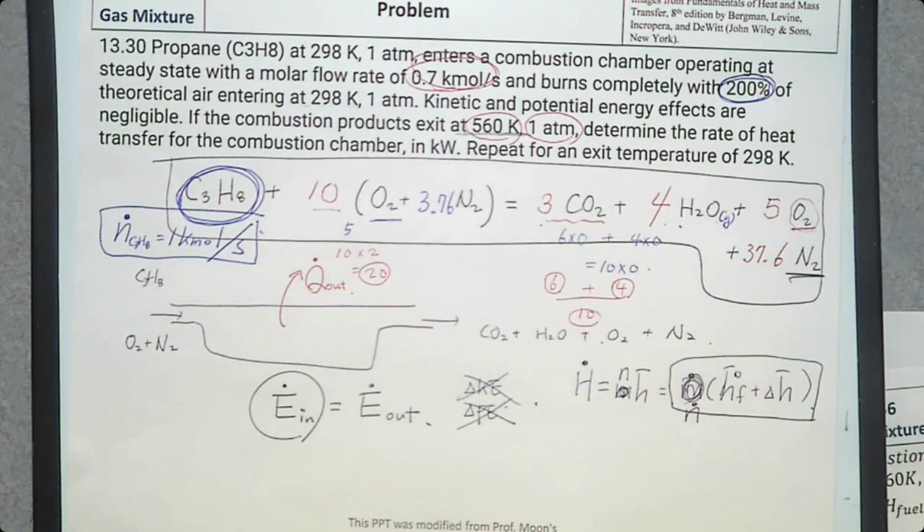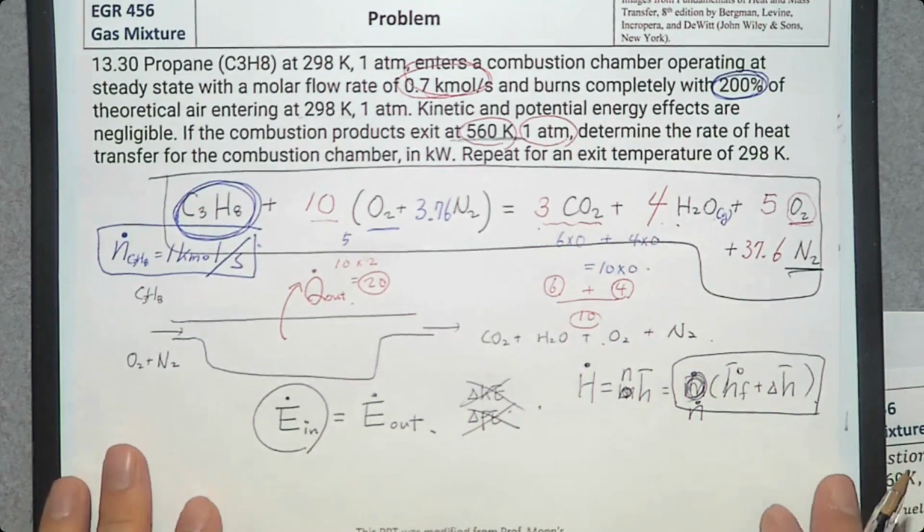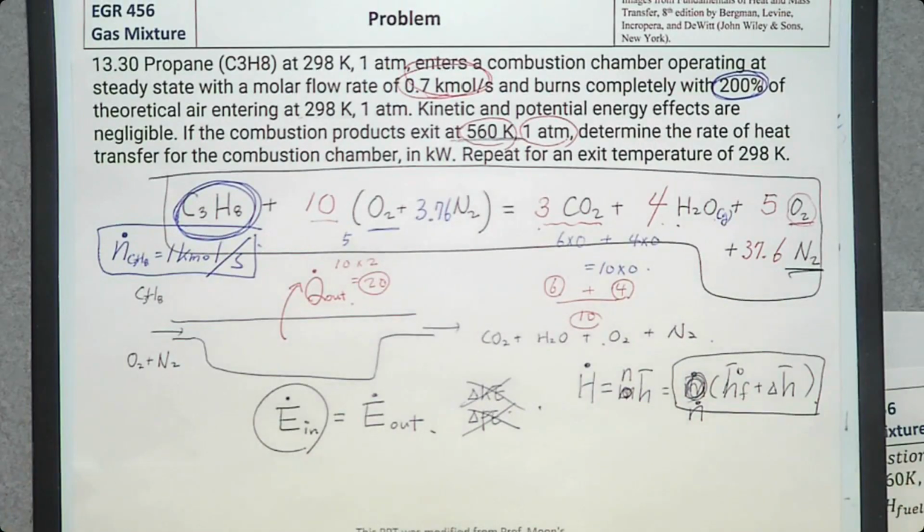What is the boiling temperature? Oh, we cannot say boiling temperature. We studied thermodynamics. What is the saturation temperature? 100 degrees Celsius. This one is greater than 100 degrees Celsius, so we know it's a superheated vapor, completely gas. But at 298, what is the phase change process? You may have liquid, you may have vapor. So we need to determine the ratio between liquid and vapor when we are not sure of the phase change process of this water. Okay? So that's what we are going to do.